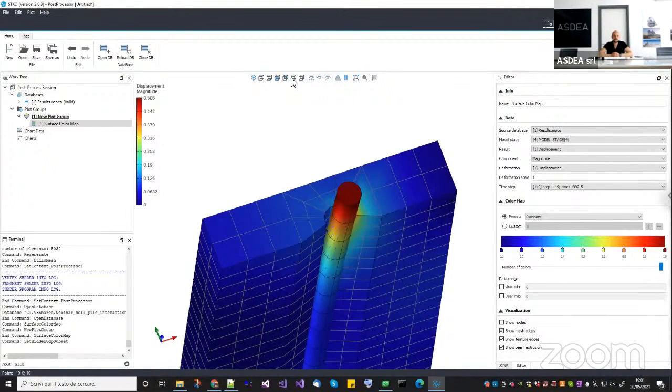Because if you use the self-weight inside the element, there is not a problem, because that self-weight is not putting a load object onto the node. It's the element itself that produces the right-hand side of the equation. So if you remove the element, you also remove the effect of the load on those elements.